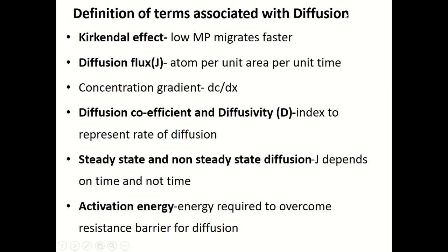I think I wrote it the opposite way here. In the case of steady state diffusion, the diffusion flux does not change with time, or the flux at any cross-sectional plane along the diffusion distance remains constant. If you take any cross section along the solid, the flux remains the same.